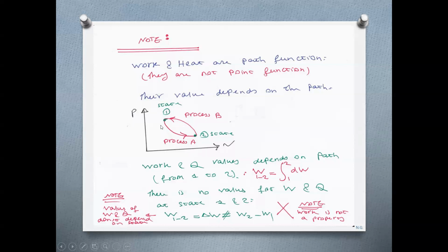And as you see, in this case, that's expansion, because as you go from a piston cylinder, for example, it can be any system. Let's consider a piston cylinder. It goes from state one to state two. You see that pressure drops, goes from P1 to P2. And the specific volume increases from nu1 to nu2. The trend of specific volume and volume is the same. So it's expansion, and then it goes from state 2 to state 1 through process B.